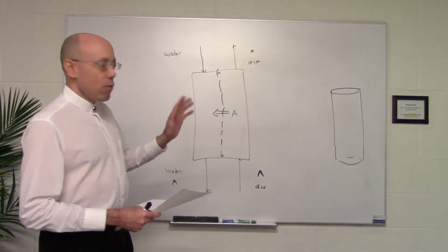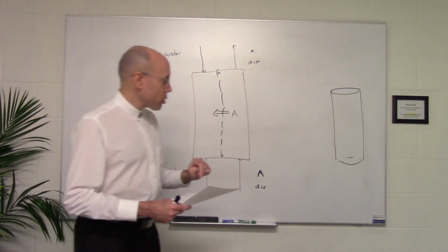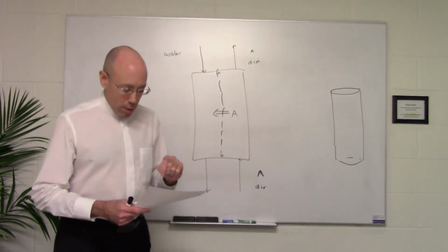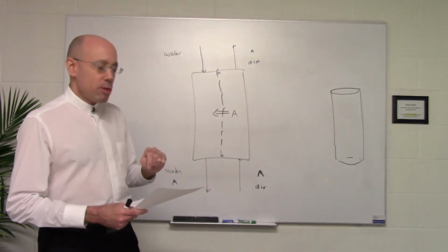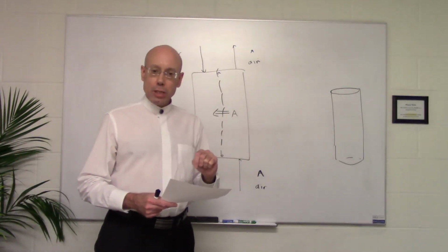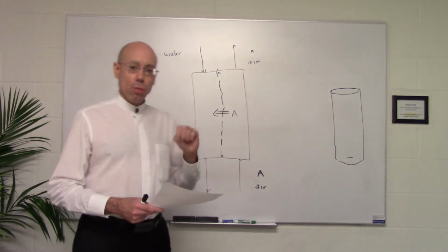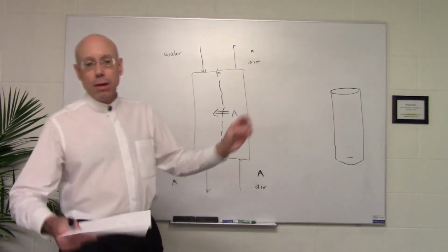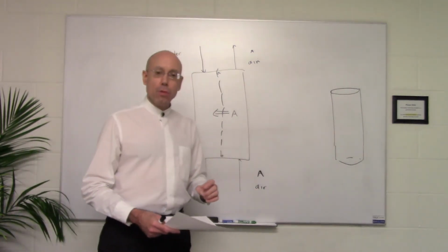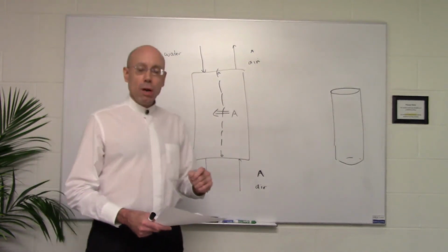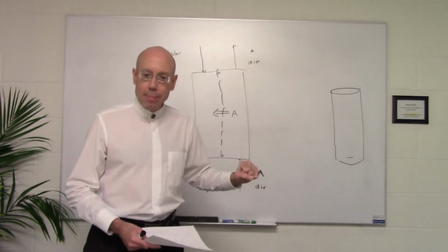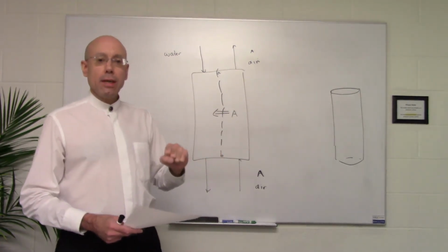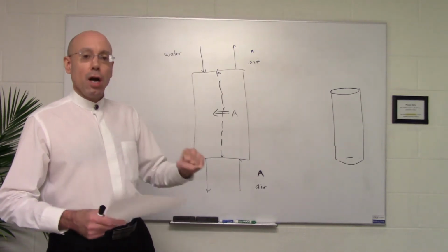In terms of overall concepts, just so that you understand what's going on and don't get confused, there are a couple of distinctions to watch for. The first one is this distinction between batch and continuous operations. A continuous operation is something that runs at 1,000 pounds per hour, day in, day out, ideally, although every so often something goes wrong, or every so often you have to do maintenance on a chemical plant. But continuous processes run at a constant rate all the time. And actually, I want to say most separations, especially large scale separations, are done in continuous mode.